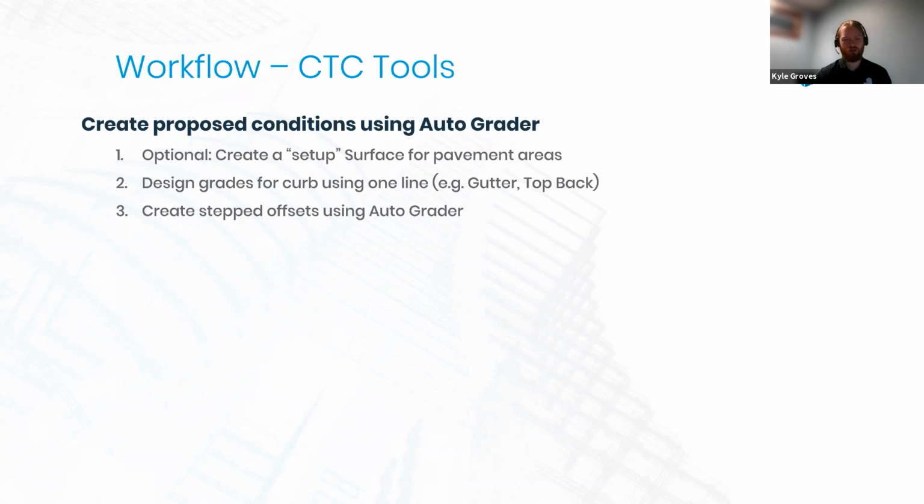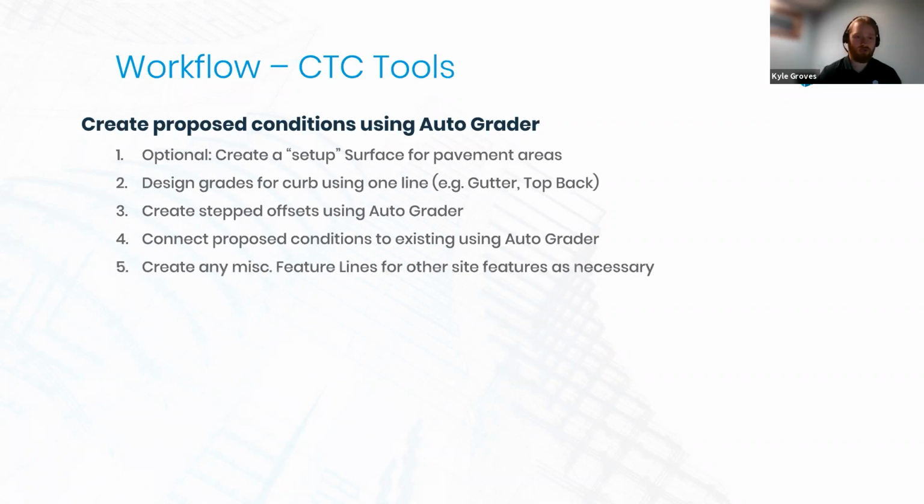We're going to use AutoGrader to create those stepped offsets. If I do need to connect back in and daylight to my existing conditions, AutoGrader does have a function for that, making it a complete potential replacement for the out-of-the-box grading tools.